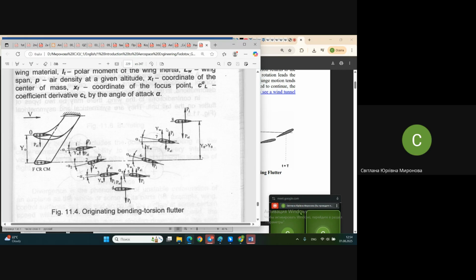And the worst situation, as I already said, is this so-called self-oscillation, which is continuous. It was enough to have some first additional portion of velocity of the aircraft for this self-oscillation to start, and after this they continue without stopping. Moreover, they may even increase in their amplitude, and become worse and worse. As we have seen in a movie, self-developing oscillations. That is the worst case of flutter, of course.